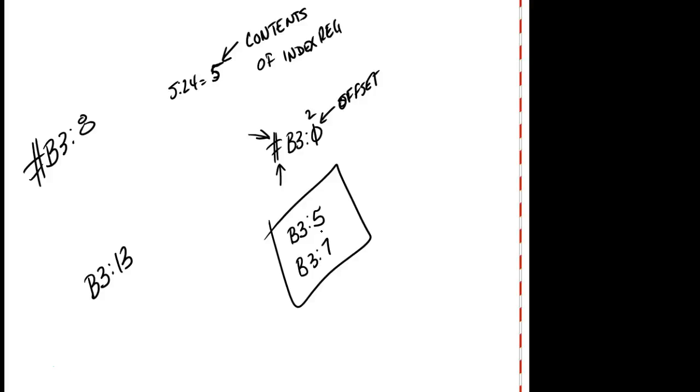Okay, now give me an actual application. What we're trying to do, normally we use the index register to automatically go through a table. We're not going to necessarily do it here because all we're going to do is shift a bit to the left or the right, and they designate that we're going to use a B3 register. I mean, using what address? Index address. So that would change your output, wouldn't it, if you shift the bit? No, we're not going to shift the index register. We're going to shift the address that the index register points to plus the offset.